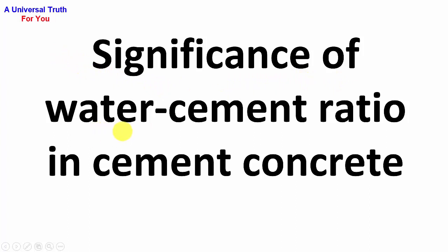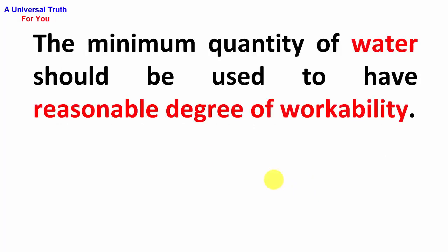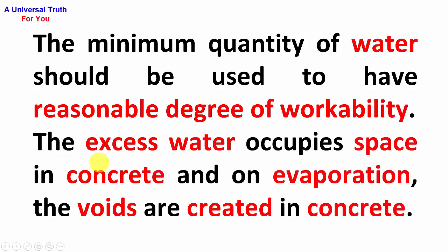Significance of water cement ratio in cement concrete. So this point will be covered. The minimum quantity of water should be used to have reasonable degree of workability. The excess water occupies space in concrete, and on evaporation, the voids are created in concrete.